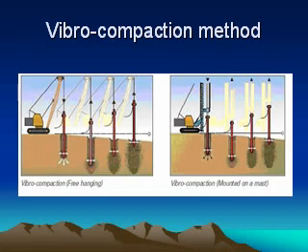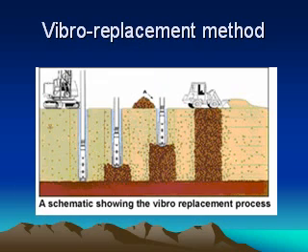Vibrocompaction is a method to help mitigate liquefaction, and it is essentially the densification of liquefiable soils by inserting a high-powered vibrator into the ground. The soil is penetrated until the required depth is achieved, and then vibrations are induced as the vibrator is pulled out. This will result in a lowering of the elevation of the ground surface, but structural fill may be placed to bring the ground surface back to a required grade.